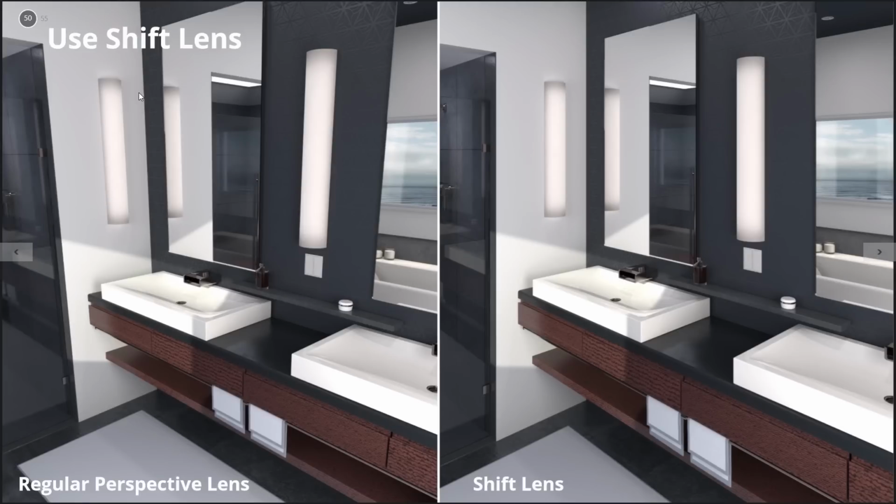Another suggestion: use a shift lens, right? Left-hand side, regular lens, right-hand side, shift lens. It's a different lens type that we added in KeyShot 6. It gives you essentially 2-point perspective. We have a blog post on the shift lens if we aren't able to get to it in the hands-on demo. It's not necessarily a more realistic appearance, but it's something that's highly desirable with architectural and interior renderings.